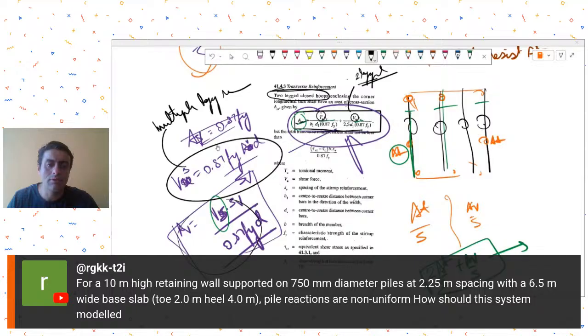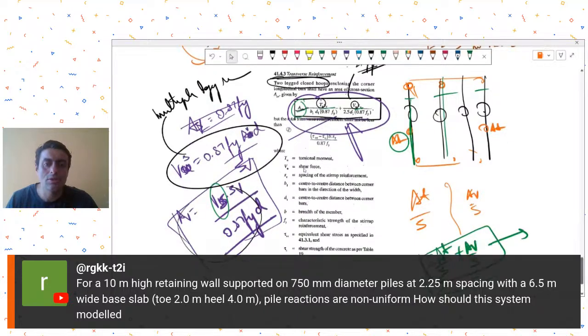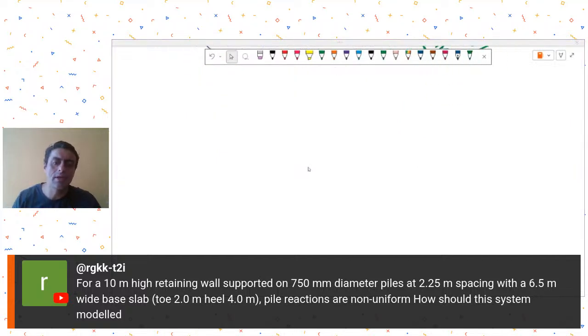First, you need to see what should be the pile spacing, what is the pile load, how much load it can resist, what is the overturning moment on your retaining wall. So first, you need to see all those things. How have you decided all these values beforehand? First, you should come up with your configuration that you want to provide.